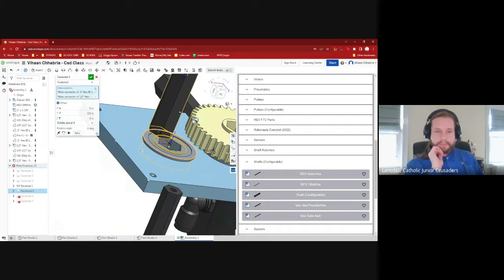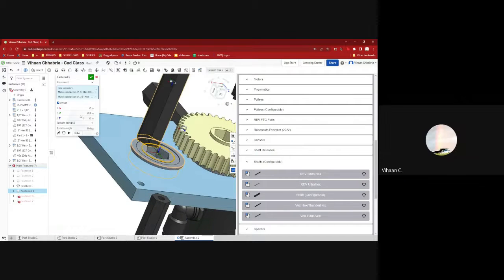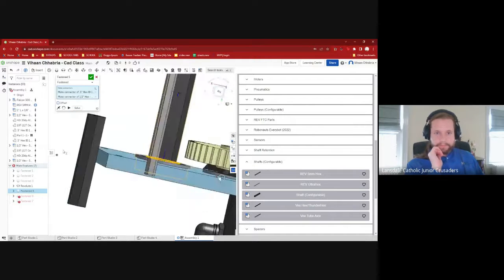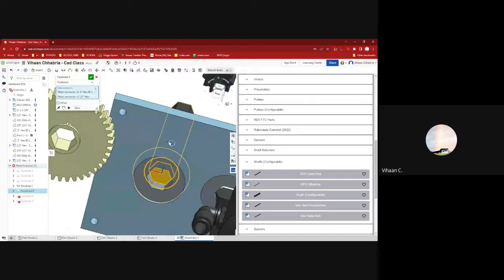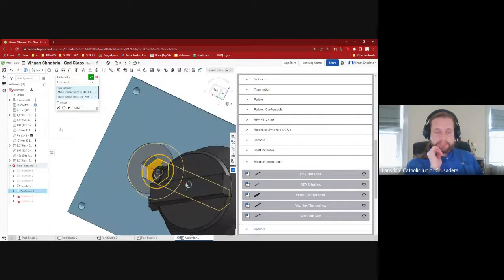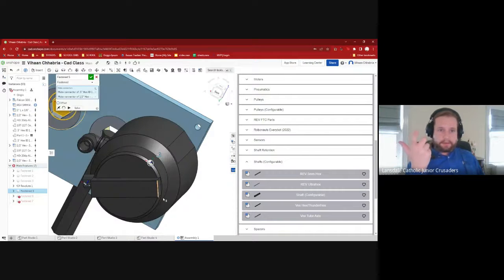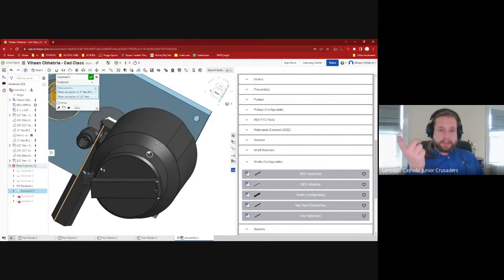Take off your offset. So uncheck the offset button, or put 0 in there. There we go. Then should we move it down a little? You can. What I would suggest to do that is change where it's mated to the other side. So delete the mate that you made on the bearing.